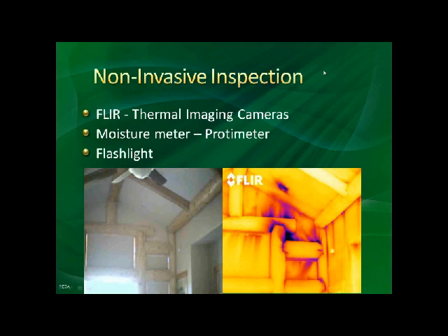For those that do high-end inspections or energy audits, you may already have a thermal imaging camera from Fluke or FLIR. You can use that to identify where the moisture is coming in. But please be advised, thermal imaging does not detect mold. It detects thermal temperatures. If there is a moisture event, it would be colder and blue. Thus, if you have colder temperatures, there is the potential for mold to be there.